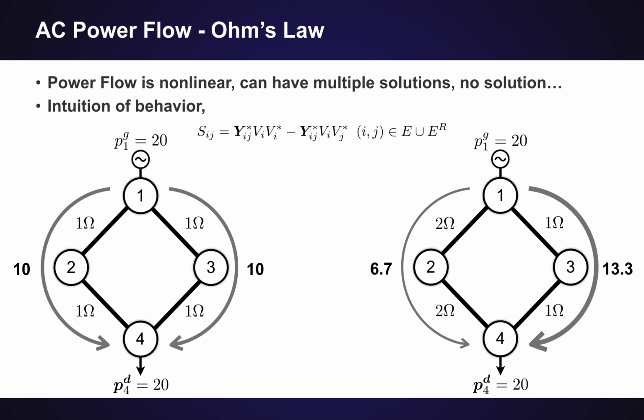Yeah, and it's maybe also worthwhile to note here that in power networks, it is typically so that we have very little ability to control how those powers are flowing. So the admittances of the lines or the resistances that are shown here, they are typically fixed and we cannot really control how large they are.